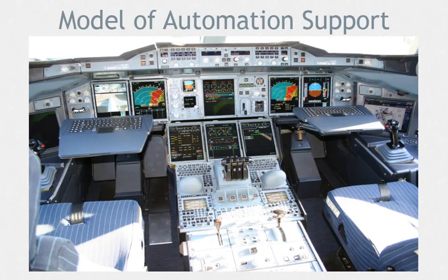This is the cockpit of an Airbus 380. Look at the image while I talk about some of the things we can do to help make actions easier in an aircraft. First, we follow the importance principle, which is to put items that are the most important or critical in the primary reach area. Next, we follow the frequency of use principle, locating things that are used frequently in an easy-to-reach area.